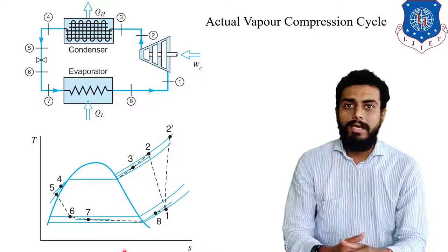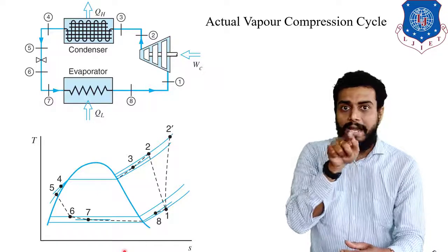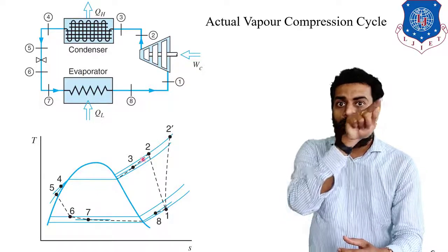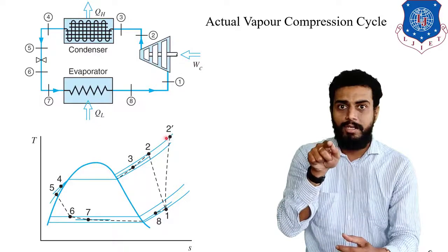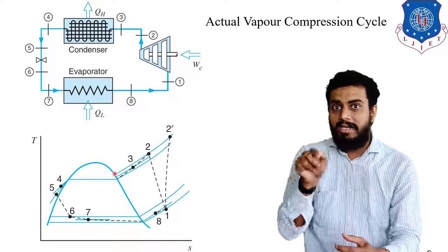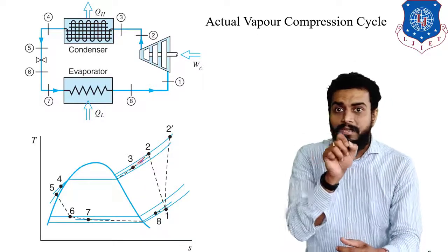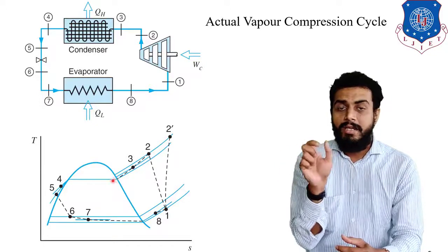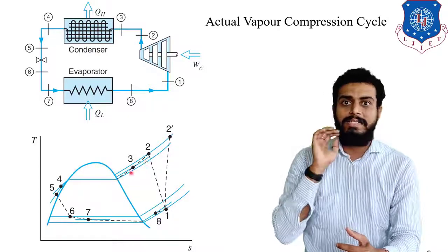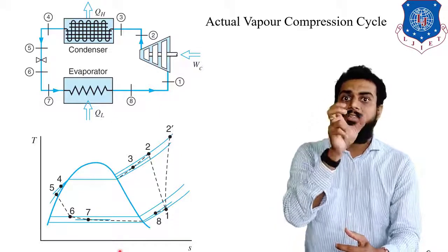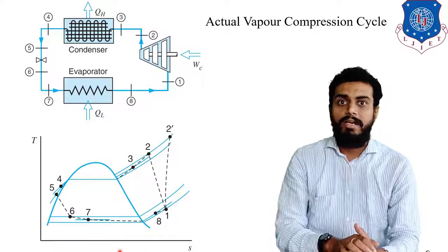That is why you can observe here that the condenser pressure at the inlet is somewhat higher. You can see the inclined blue line in the superheated vapor region, right? The topmost line is showing high pressure. As soon as it enters the condenser, due to irreversibility, the pressure might fall by some amount. So now you can see in the condenser section, in the latent heat region, the pressure line shown is the low pressure line, right? I hope you can understand this. So in a condenser in real life, the pressure might not remain constant. That is also another real life phenomenon.